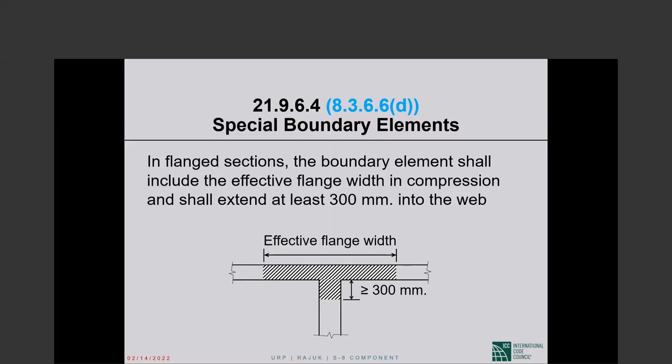In that sense, it may be preferable, but I would emphasize that it is applicable only to cantilever walls hinging at the base. Starting with 318-14, it will be applicable only to walls with height to length ratio larger than or equal to 2. So there are conditions of applicability. You cannot apply it to any wall, whereas the conventional approach applies to any wall.